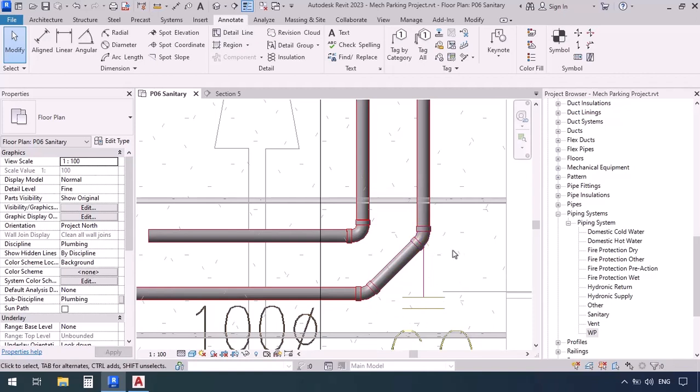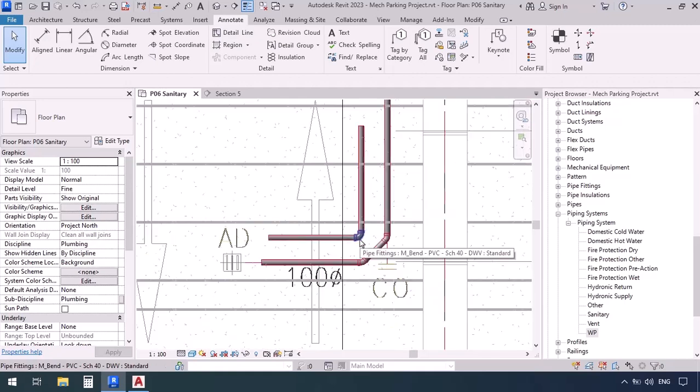This actually prevents recurrent cloggings in the pipes, as in the water would move here and go further through a light angle. There are some exceptional cases where we would need to use a hard 90-degree angle, but as long as that's not the case, you would have to use two 45-degree angles instead. Now I'm going to delete this one.